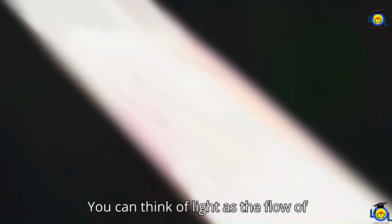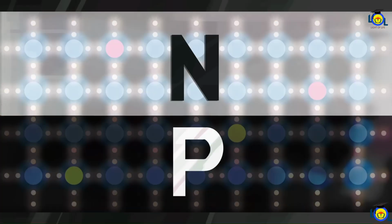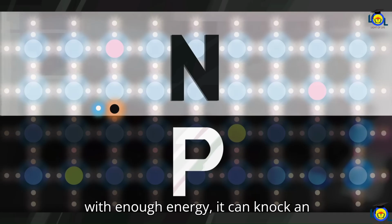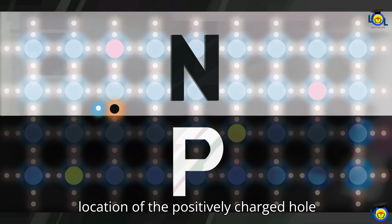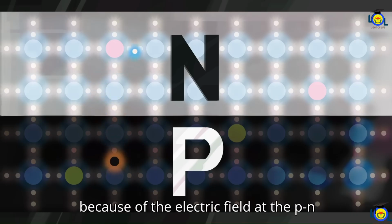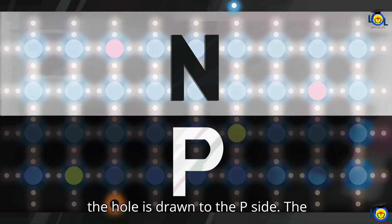You can think of light as the flow of tiny particles called photons, shooting out from the sun. When one of these photons strikes the silicon cell with enough energy, it can knock an electron from its bond, leaving a hole. The negatively charged electron and the positively charged hole are now free to move around. But because of the electric field at the p-n junction, they will only go one way. The electron is drawn to the n side, while the hole is drawn to the p side.